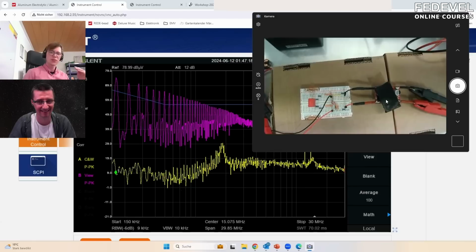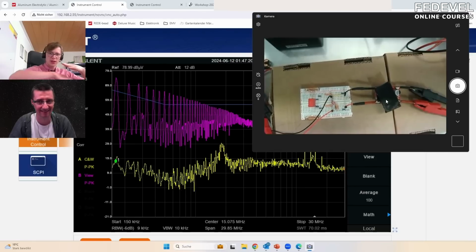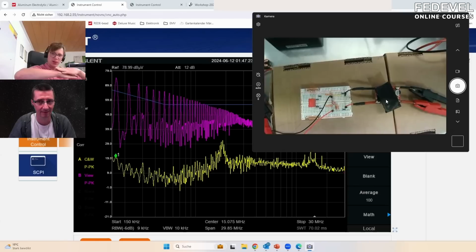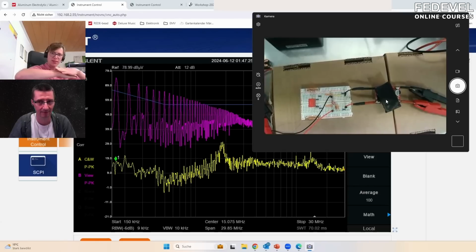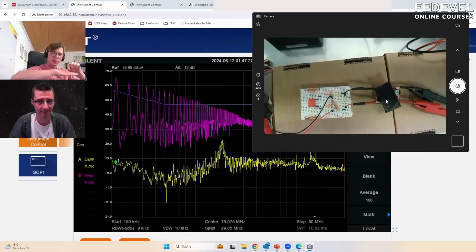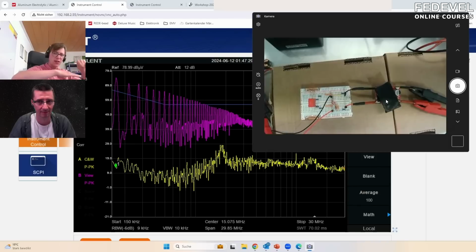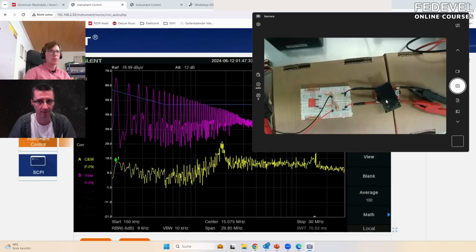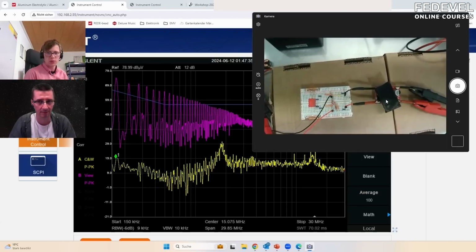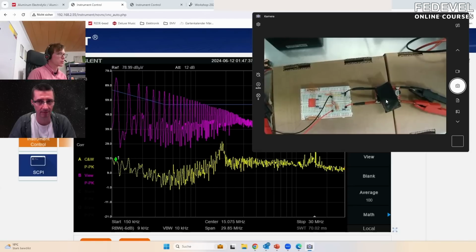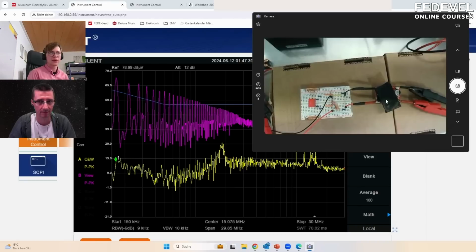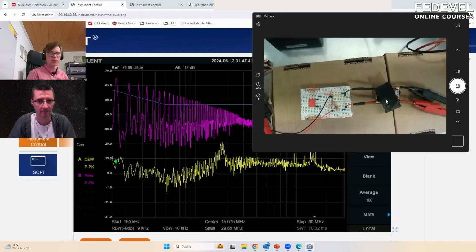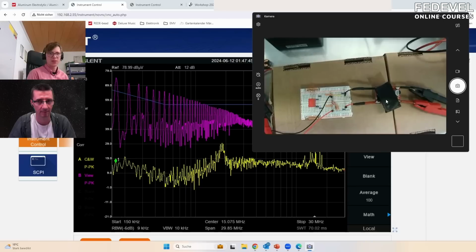are very often also the switching node. And when you come very close to the housing, you have this high capacitance in between. And this is the reason why the people later on need a capacitor back to the circuit when it is isolated. But here we have no common mode filtering at the moment, and therefore we have this kind of noise. And common mode filtering is actually very expensive.